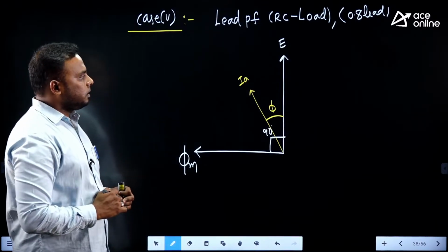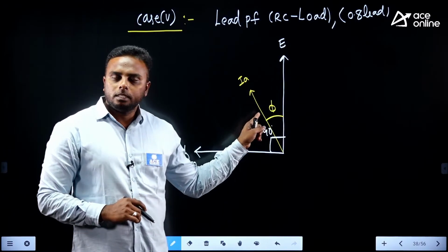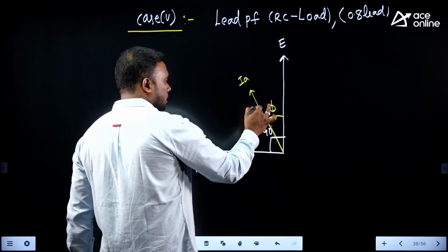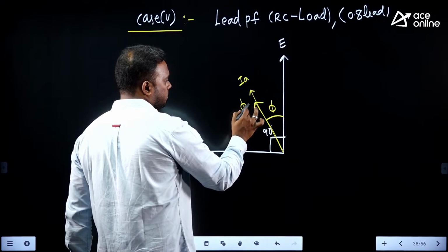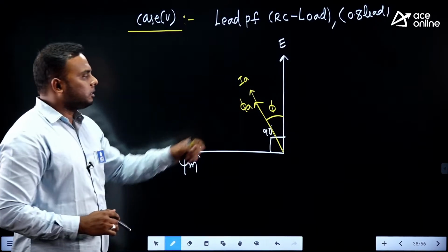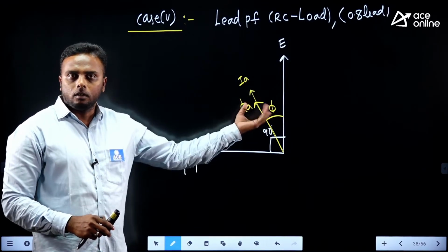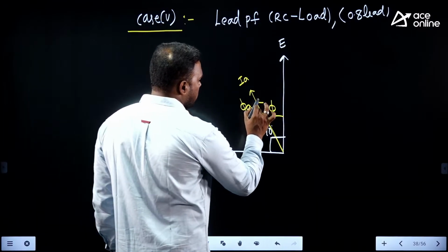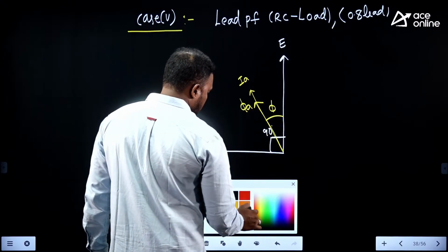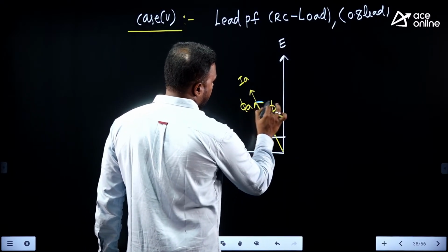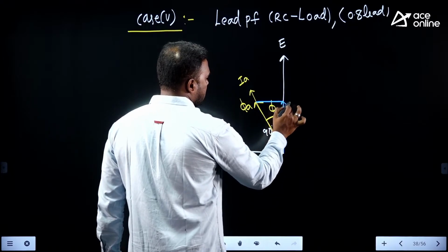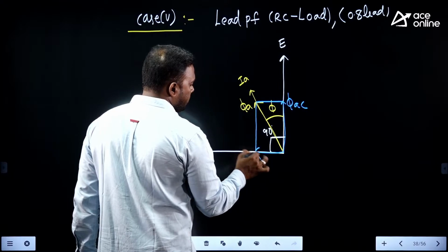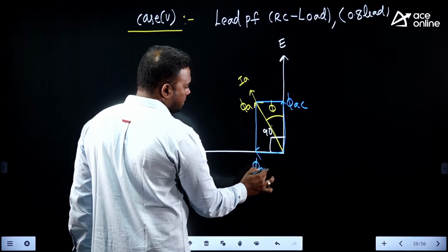Okay. Next, when there is an armature current, armature flux will develop which is in phase with this current. This is the armature flux. Now this armature flux is not at 90 degrees to this, nor in phase with this; it is in between. So this armature flux we resolve into two components again. One is cross magnetizing, phi AC, and the other is along phi AM, in phase with the main flux, which is the magnetizing component.